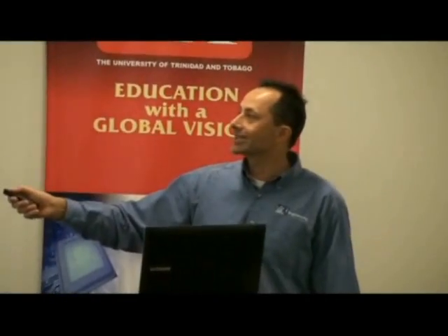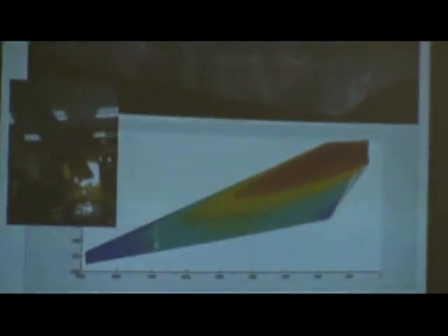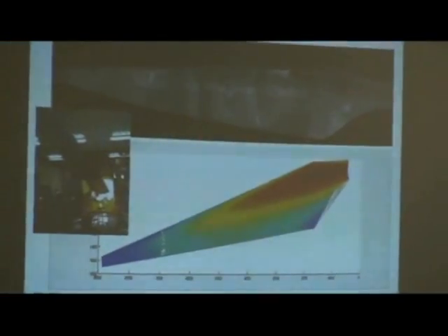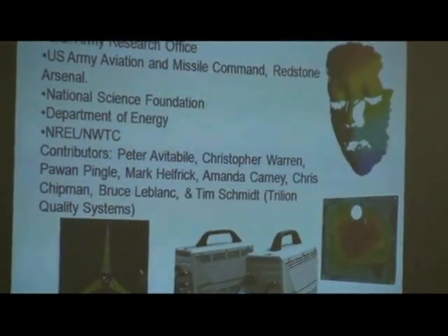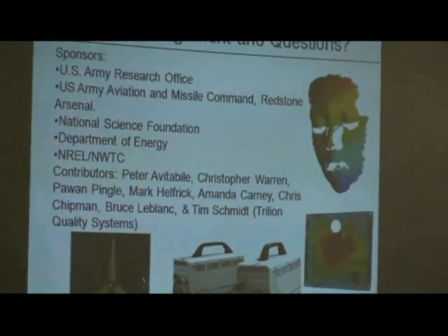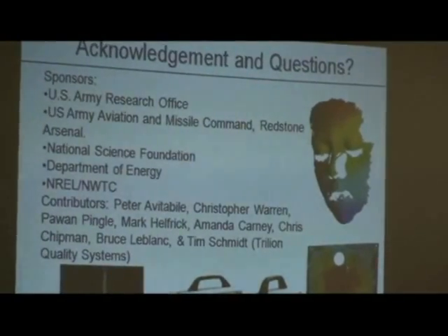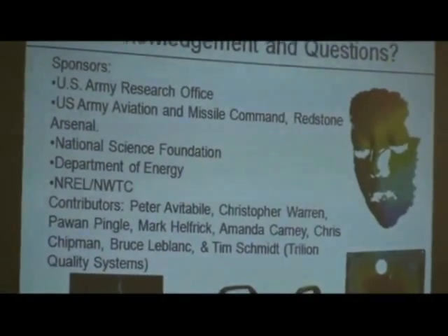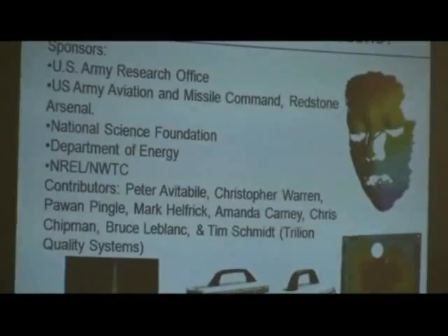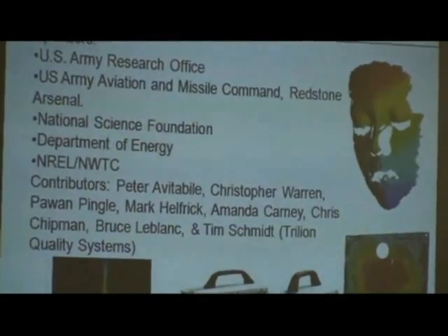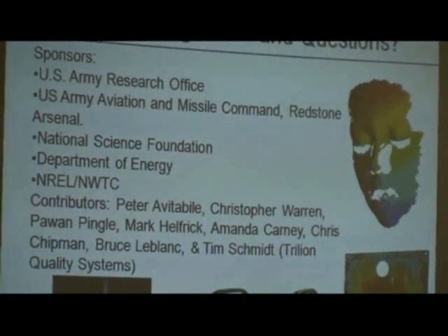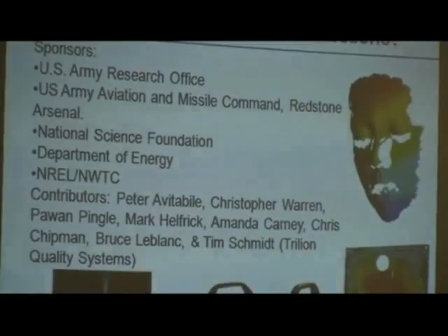So what we did was we took 16 different images. We stitched them together. And so here's the complete displacement of that 9-meter blade. And so we're able to get the full field displacement measurement. And likewise, we could do the same thing with strain. So that gives you a summary of digital image correlation, how people typically use it, and how we're trying to exploit it for vibration analysis and also for structural health monitoring.